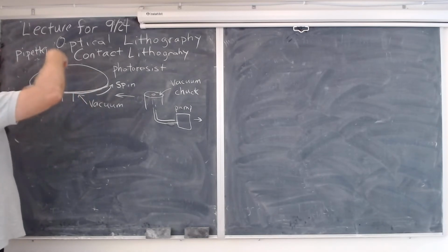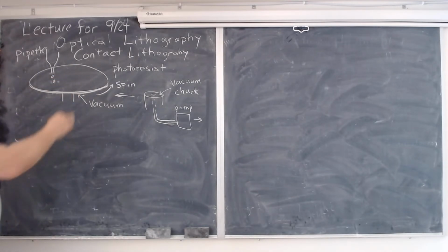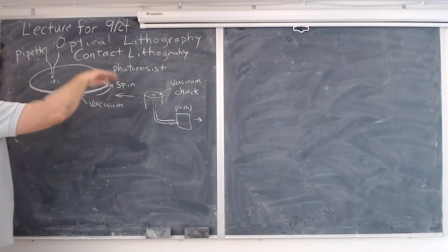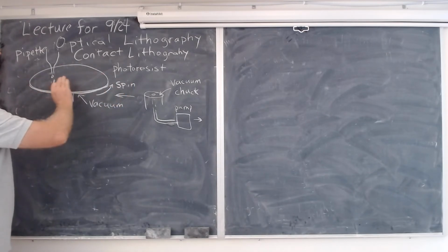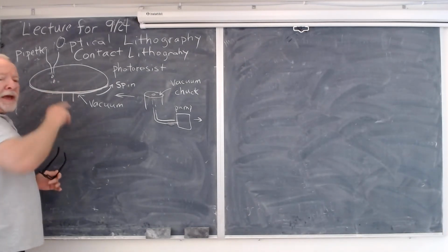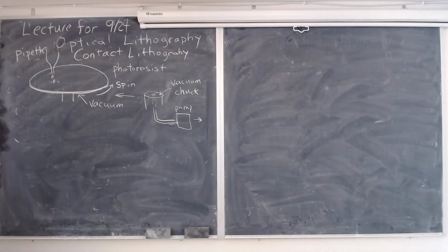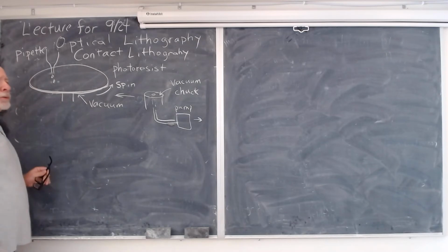You don't want to put down a pattern with your dripping that leaves a hole in the middle, because you're trying to make a coating by spinning it, and so it's moving outward to the edges of the wafer. You don't want a situation where after spinning you're left with a gap in there. Depending on the size of the wafer or the shape of the piece you're working on, there can be some thought as to how you put your drip pattern down on the wafer.